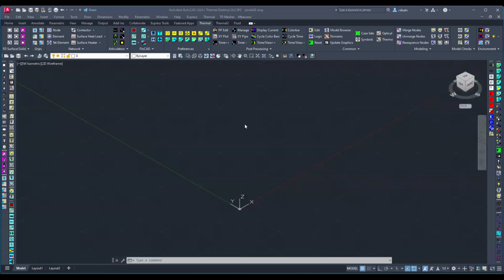Hello, this is Chris DeSalvatore, and in this tutorial, we're going to make a set of parallel plates, and we're going to calculate the Radks, which is the thermal radiation exchange factors, from them into space and between them. They're going to be identical parallel plates directly opposed to each other, and the length and width will be 10 by 5 inches, and the plates will be separated by 12 inches. We're going to define the lower plate as surface 1 and the upper plate as surface 2.